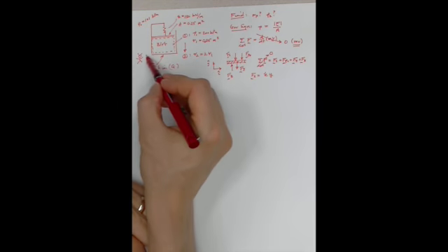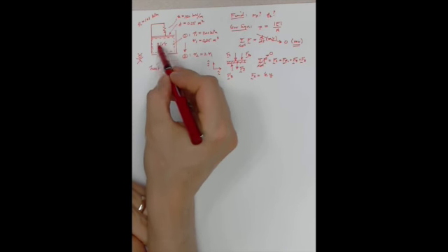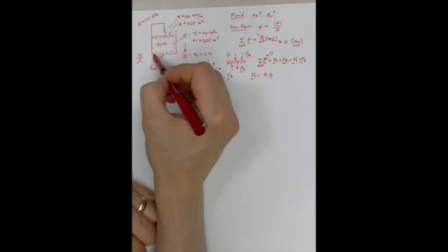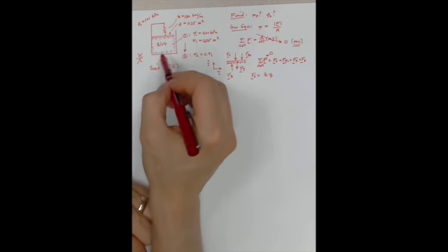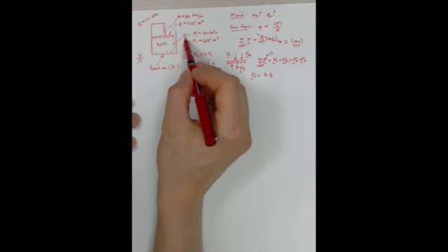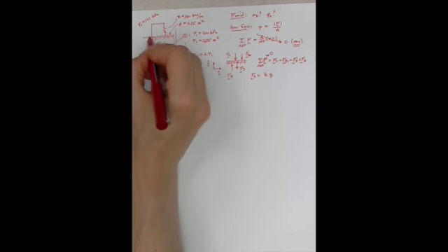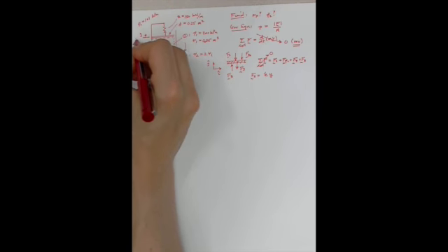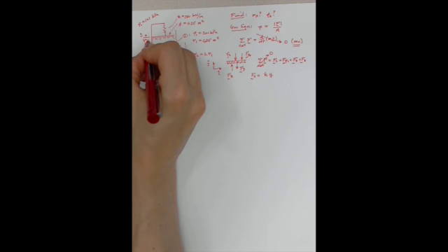In class, we defined the coordinate y to have its origin down here. That was because the spring force was 0, or the spring was unstretched, when the piston was all the way at the bottom of the cylinder. In this case, the spring force is 0, not down here, but at the initial location, state 1. So it makes sense that we would define y to go up, and that this line would be y equals 0.